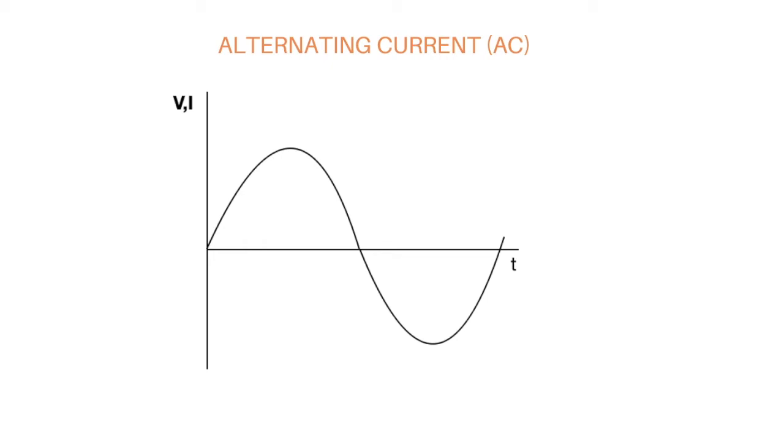So for example, at home, you use 220 volts. That is what is coming out of the wall socket, right? But that is not actually what Eskom distributes. Maybe they might distribute 2000 or 4000 volts or whatever, but it gets to a small unit called a transformer, and it can step it down quite easily without losing much power, right? So the efficiency using alternating current is much better than using direct current, right?